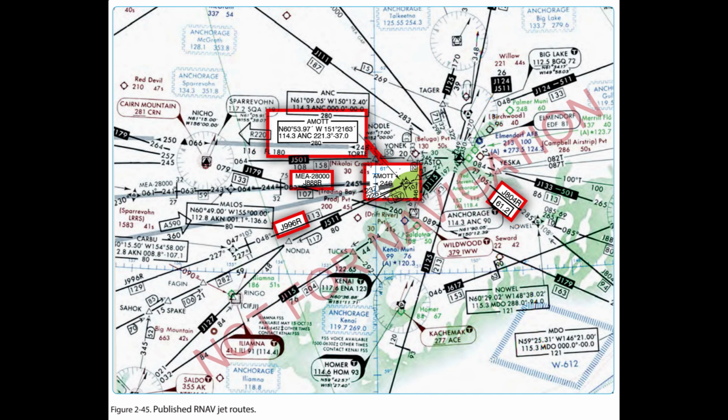Pilots flying aircraft that are equipped with approved area navigation equipment may file for RNAV routes throughout the NAS and may be filed for in accordance with the following procedures. 1. File airport-to-airport flight plans. 2. File the appropriate RNAV capability certification suffix in the flight plan. 3. Plan the random route portion of the flight plan to begin and end over appropriate arrival and departure transition fixes or appropriate nav aids for the altitude stratum within which the flight is conducted. The use of normal preferred DPs and STARs, where established, is recommended.